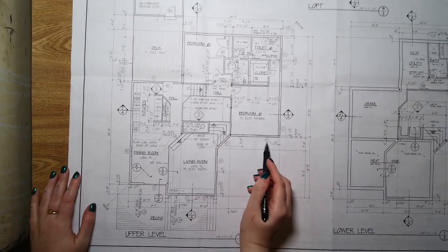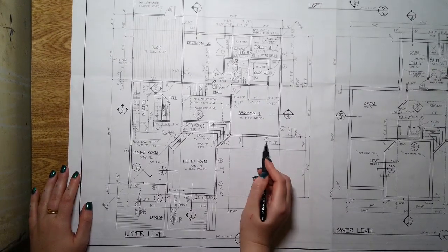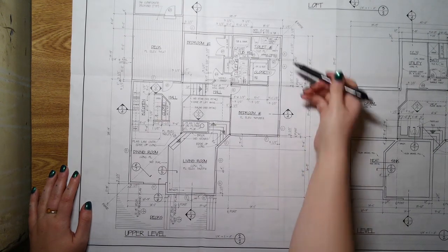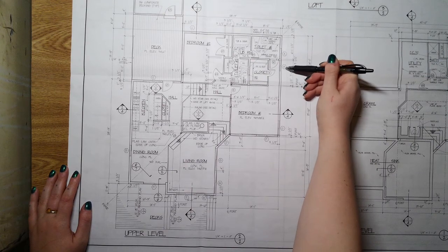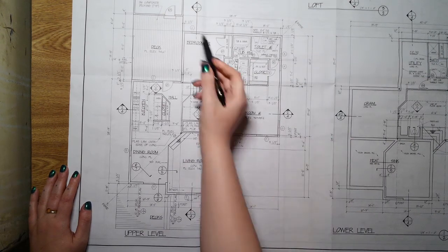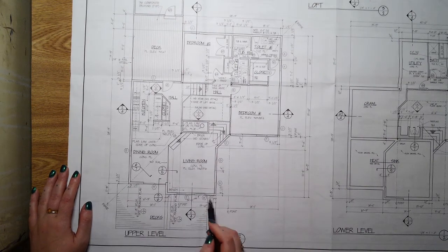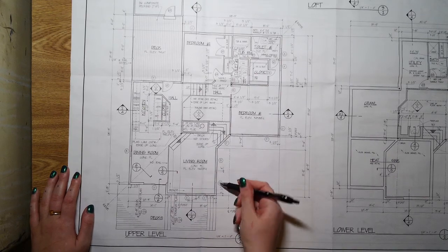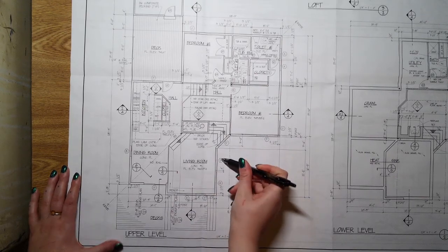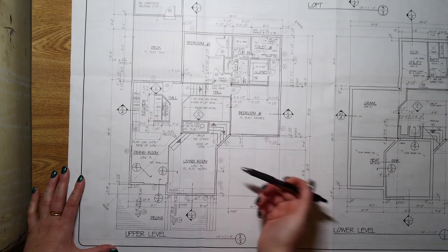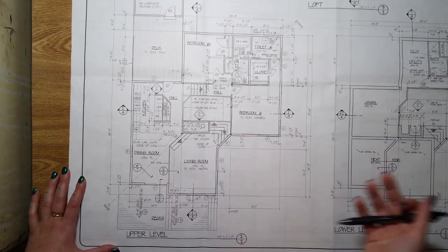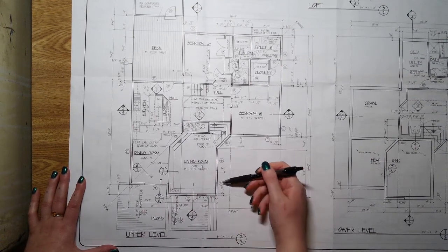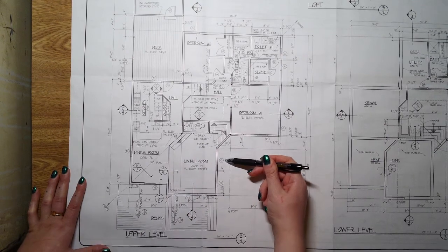We can see that all of the windows have this little hexagon marker, and some of them have the exact same letter in them. So this is window type A, this is window type A, this is C, and this is C. We've got E, E, E, and so forth. This window here is window type G, and so is this one. Rather than putting it in the schedule, the little chart that lists my window types, twice, we just say that these windows are both the exact same window, spec-wise.